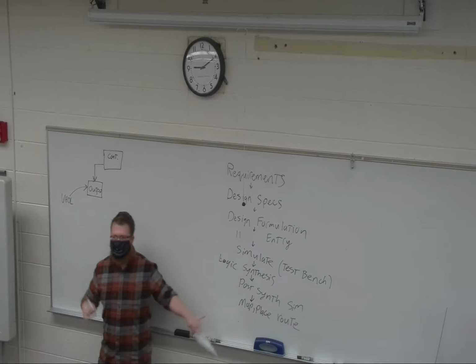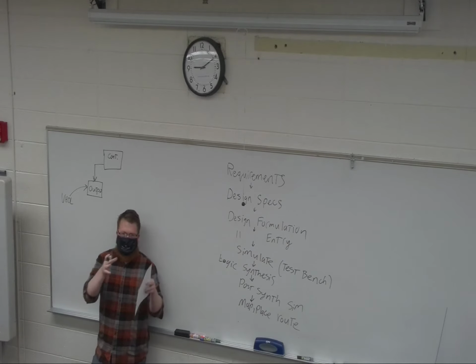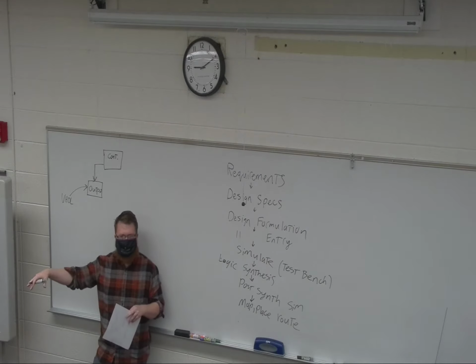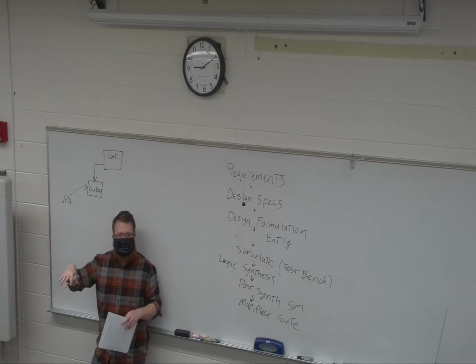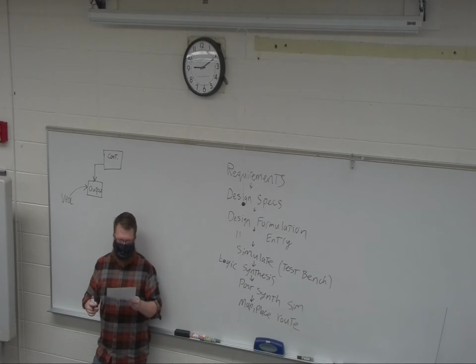You'll then move on to map, place, and route, right? And what that means is taking the logic that is formulated and actually putting it on the device. So figuring out where it goes on the device, placing it on the device, and then routing the connections together.